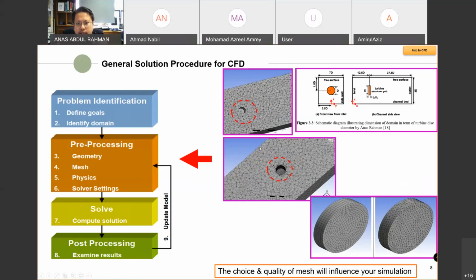You can see the difference. If you use global meshing, you can see how coarse and big the elements are within the object. But after refining the face and the edges of the object, we have several hundreds or thousands more elements within that region. Here we can count 1, 2, 3, maybe just about 8 elements compared to these thousands of elements.